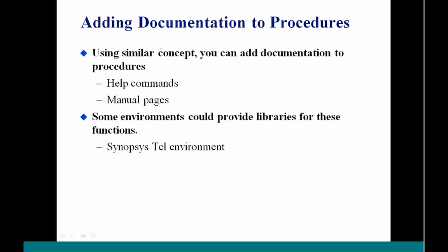So you can specify the command, which is called define_proc_attributes, and you specify your procedure name followed by -info, and then you specify a string which contains the information to display.